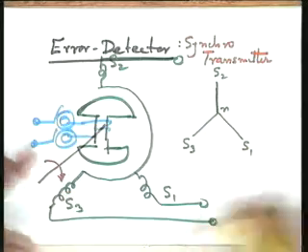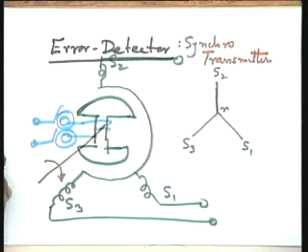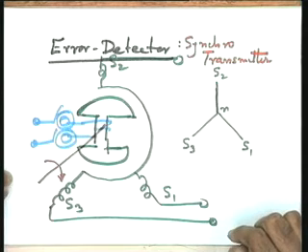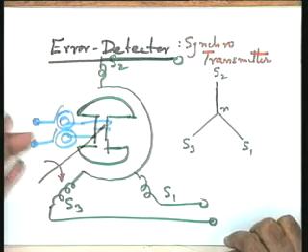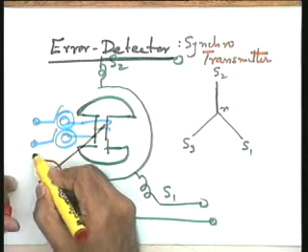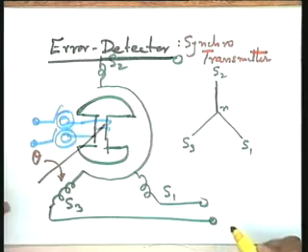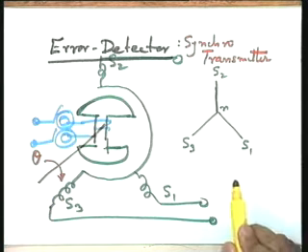Okay. In this particular case, the input output arrangement you must see: the AC voltage to the rotor is a fixed voltage, it is the auxiliary supply. You are not changing this voltage. What you are changing is the rotor position, and in response to this particular rotor position, the three voltages at the three terminals S1, S2, S3 should change, and the information about the rotor position theta should be carried in these three voltages. Okay. Now help me, how will these three voltages be linked to this particular theta? The relationship to theta is to be determined.